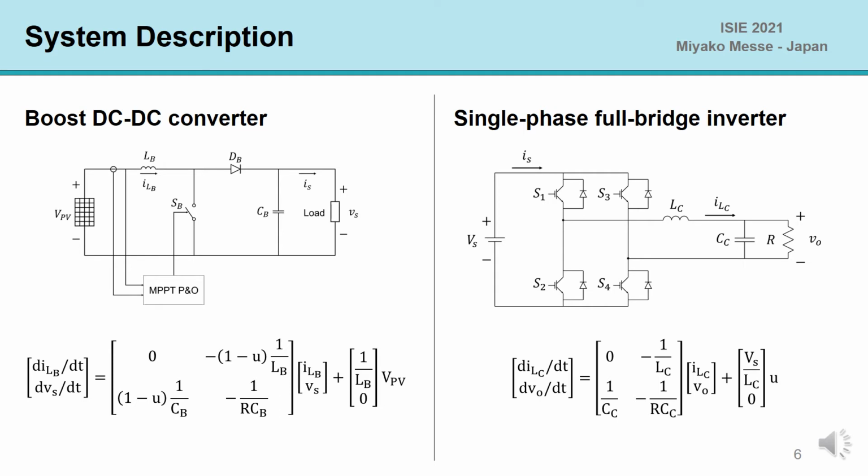To complete the PV generation system, a bus converter and a single-phase full-bridge inverter are used, starting from analysis in the state space model to dimension their components according to the established generation capacity. Also, pulse width modulation is used to generate the activation signal for the inverter transistors.